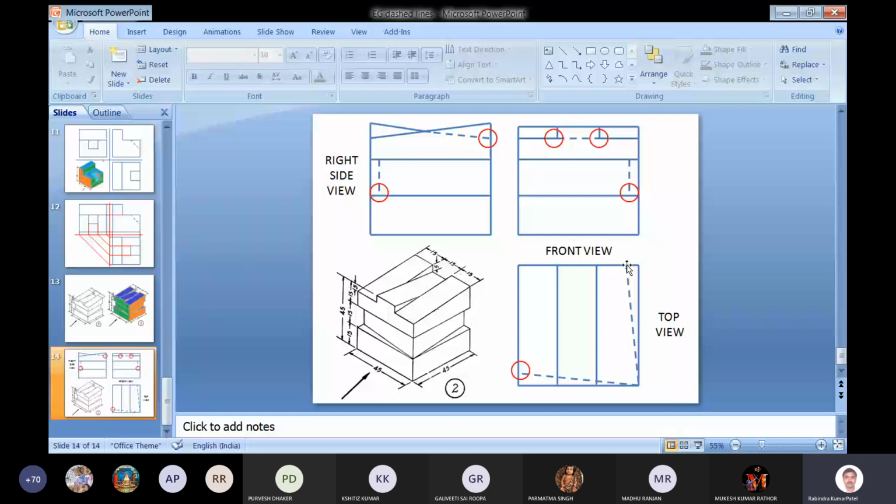So why have I shown red circles? This is because there are different places where a correction is needed. Like here, the dashed line should touch the continuous line. Here the dashed line should not touch this corner point. Here also the corner point should not be touched by the dashed line. Here this dash should touch the continuous line.